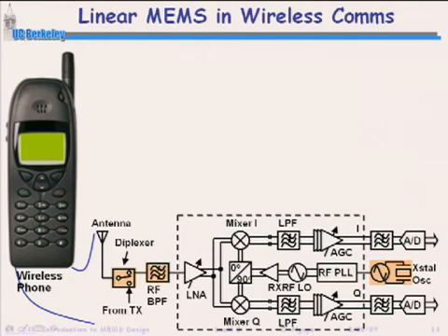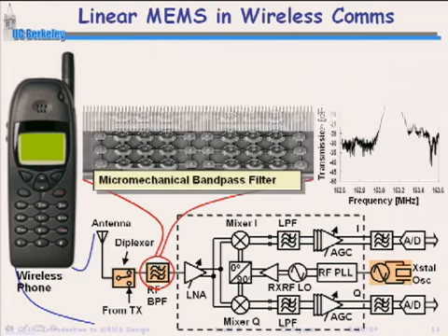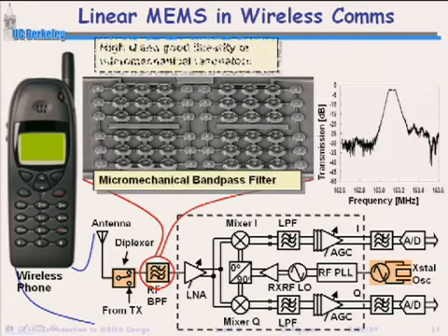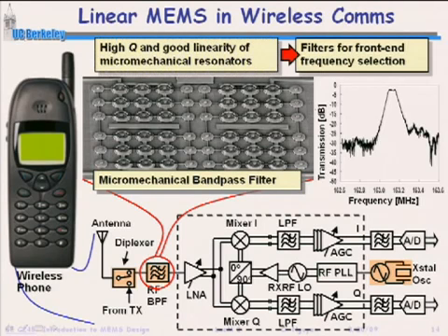All right, so you need this filter in order for this to work, and this filter might be implementable using this MEMS technology. In fact, it is implemented right now using a different kind of MEMS technology, which is the F-bar. It's a thin film bulk acoustic resonator. And all of your cell phones, well, at least your CDMA cell phones, have this.